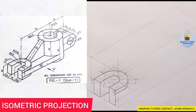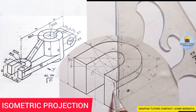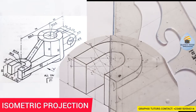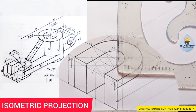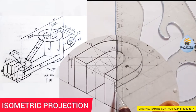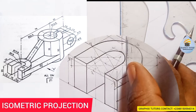So aside that, if you look at the figure very well, there's another circle at the base too. So I'll also do the same thing. Bring this line downward. Remember that I'm always placing my set square on my t-square, right? So don't get it twisted. So I'll place it, bring it down this way. Right?